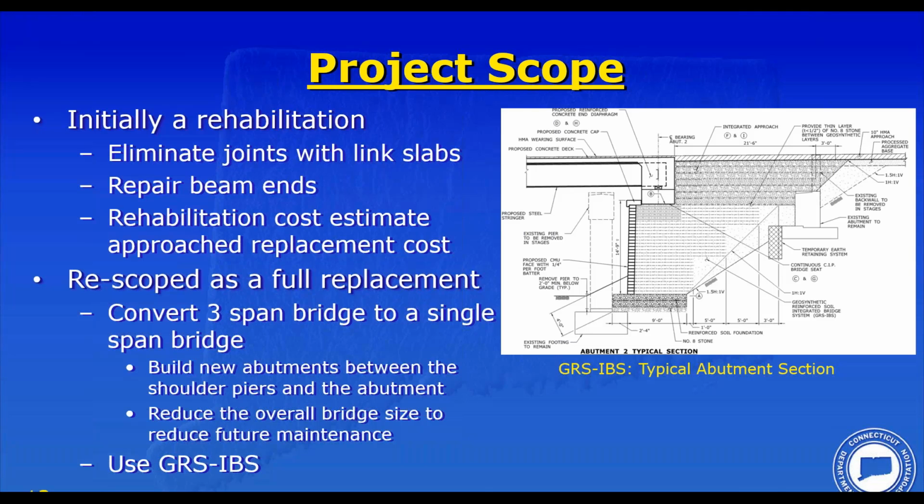So we have a standard specification we developed with Connecticut DOT, working with their soils and foundations unit, and including the use of wet cast block, which is unusual. Most states do not use wet cast block; they use dry cast block.